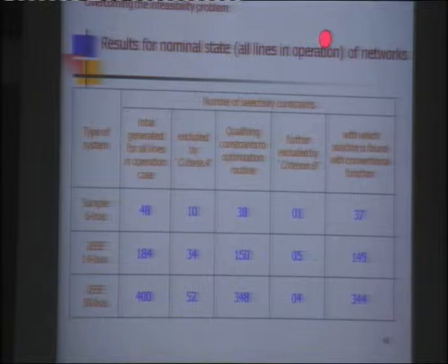And then recently another concept known as adaptive protection is also being introduced. In adaptive protection, the fault currents are monitored online according to the latest changing conditions. Then settings are calculated. That means the online settings are calculated by, let us say, this mathematical optimization procedure, and at the same time these are transferred also. But it is not so easy.